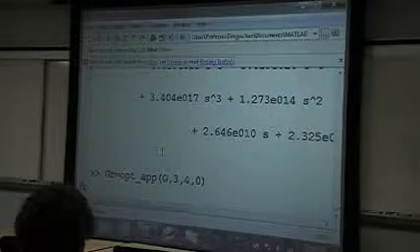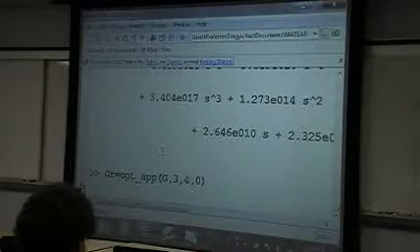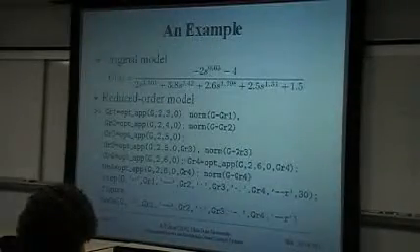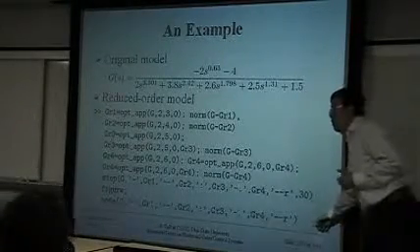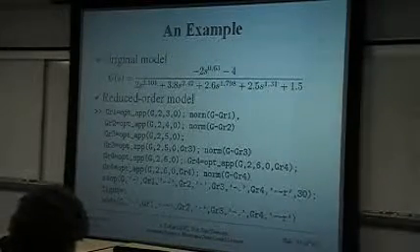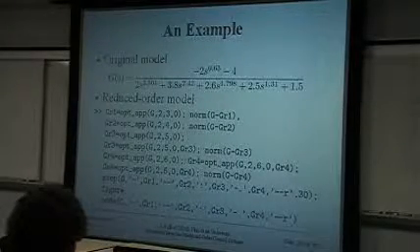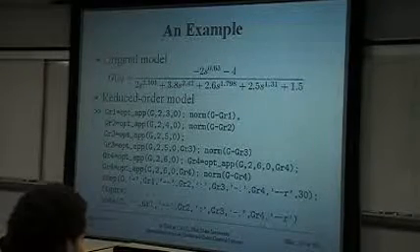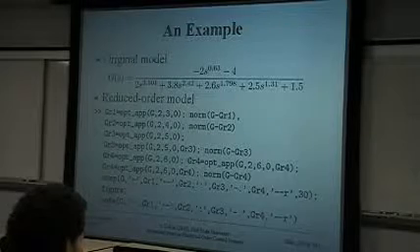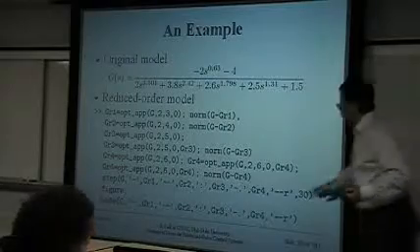How do you know you're getting a good approximation? You can try different combinations and check the final fitting results. But I will send that one later to you. Actually, this is the code I use. You can compare either the Bode diagram to see whether the fitting is good, or you can compare the norm of the error. You can find G minus GR, which is the error, find the norm of it and see whether it is small enough. I think the best way is to use the Bode diagram comparison.